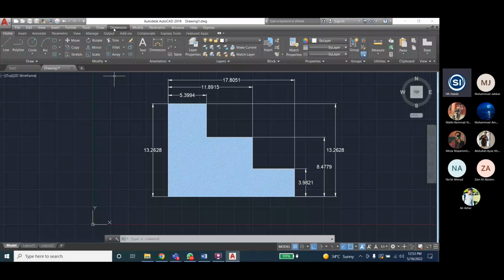And it will say enter new value of dimension variable. Because I already updated from 0.18, 0.5 is appearing here, and 1 is appearing here. Right now I want to change it, you will change to 2, and I will change it to 1. Okay. You will change to 2 and press enter. Only one time press enter. Okay. And then it will say enter variable name again.